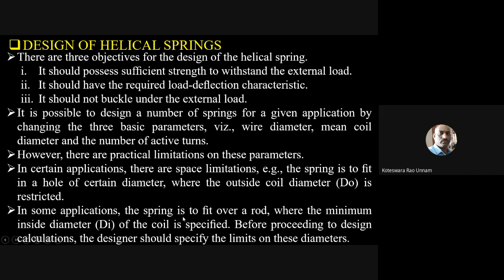In some applications, a spring is to be fit over a rod where the minimum inside diameter of the coil is specified. Before proceeding to the design calculations, the designer should specify the limits on the diameters. So, while we are saying that these are the three basic parameters we need to determine for the design of a helical spring,